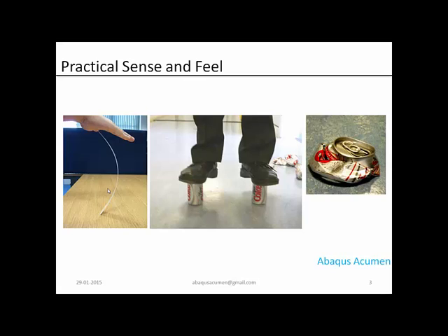As you start applying compressive loading on the steel rule, at one particular situation, with little increment in load, the steel rule buckles. You see a suddenly high deformation at one particular load, and that load is called the buckling load, or critical buckling load, or a bifurcation point in buckling terms.